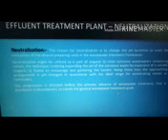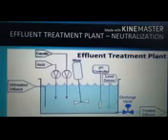Therefore, the incoming solution is pH adjusted in accordance with the ideal range for precipitating metals as hydroxides. This step is conducted before the primary step of wastewater treatment, that is clarification or decantation, to fulfill the general wastewater treatment goals. So in an ETP, neutralization involves the caustic and acid mixer and pH controller, level sensors, and untreated influent and discharge valves, and treated effluent is available in this neutralization structure.